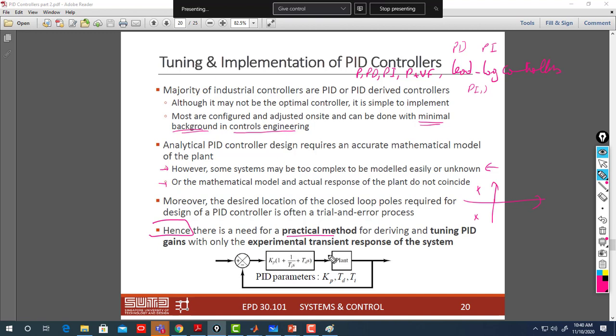Or wire it, but when you wire it, you will have the effect of the wire, especially if your system is small. The wire weight will be somewhat equivalent to the weight of the robot. Otherwise, if your self-balanced robot is big, you can neglect the effect of the wire. So you can do it wirelessly and get the output to your screen.